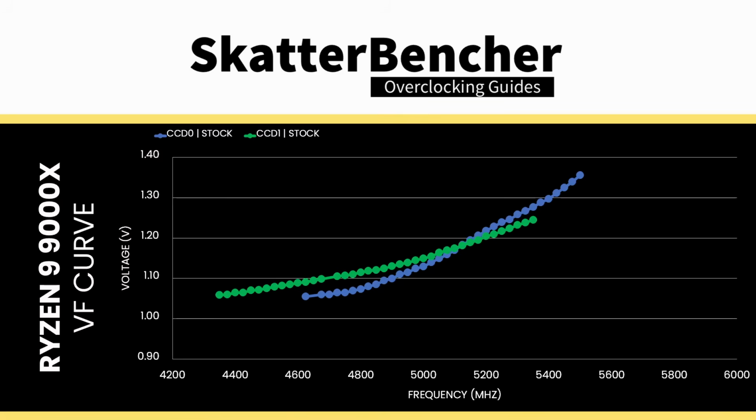We can immediately make a simple and redundant observation. The higher the frequency, the higher the voltage. For example, CCD0 requires only 1.129 volt for 5 GHz. However, we need 1.355 volt for 5.5 GHz. Although it's not obvious from the VF curve, the maximum allowed voltage is 1.355 volt when all 6 cores in a CCD are active.